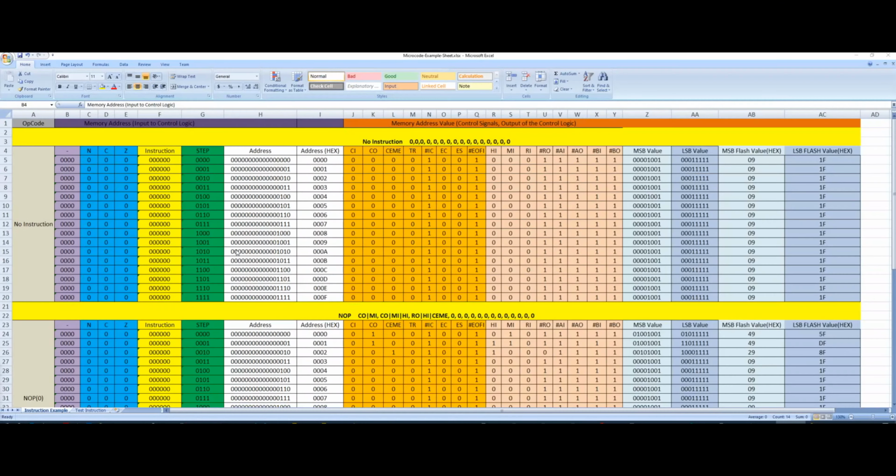All right, so we're ready to test the module. However, before starting the test, we really need to write something into those flash memories, because by default from the factory, they're all set to the value FF on all memory cells, and therefore there would be no way to test them and see if they're outputting any signals. So at least we need to come up with some test instructions to test if we are actually outputting any signals.